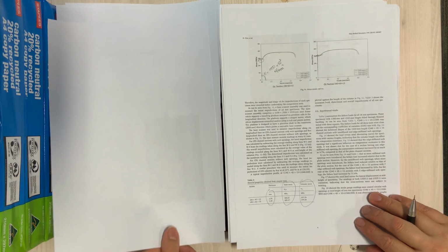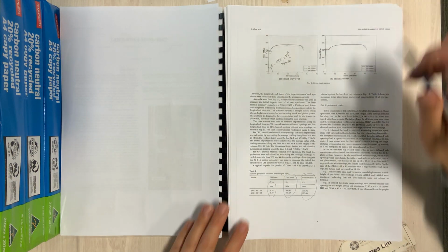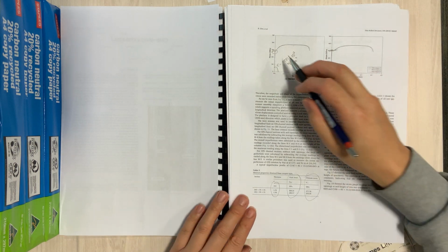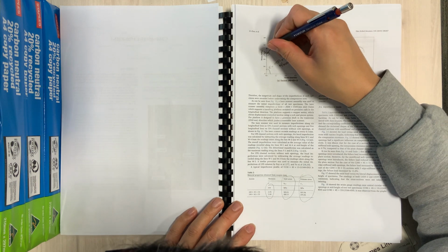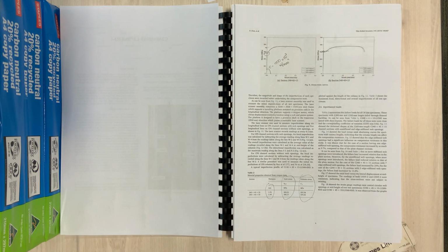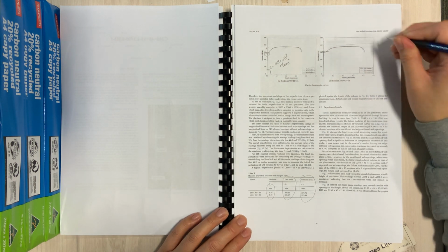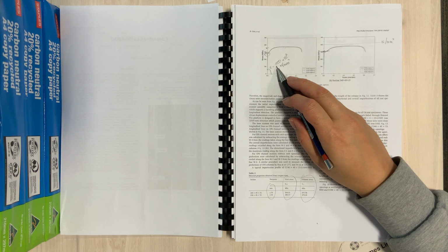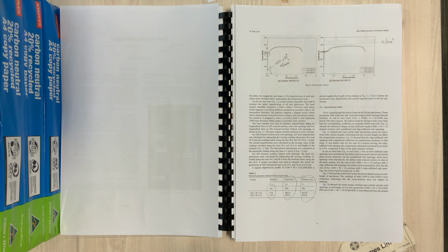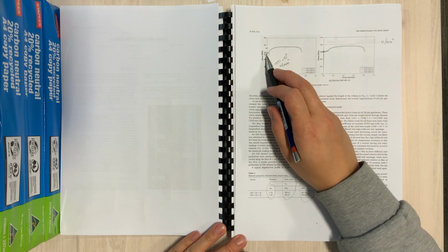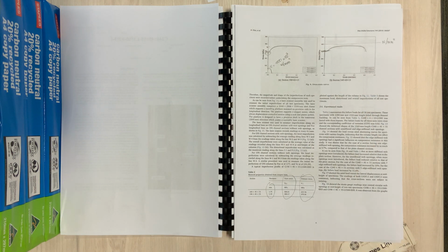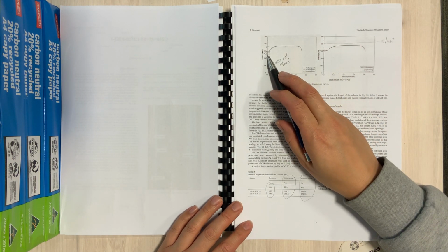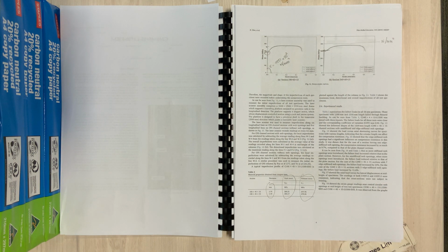eventually it would fracture. So when we do these experiments, we plot the stress strain curve, and we can see that for steel, the yield stress is maybe about, or the ultimate stress is maybe about 300, certainly less than 400 newtons per millimeter squared. So it's quite a nice idea to have these things in your head so that you've got a reference point. You know that the Young's modulus for steel is about 200 times 10 to the 3 newtons per millimeter squared, and you would know that your yield stress, of course, would be under the ultimate stress, and you would know that typical values would be about maybe 300, ranging all the way up to 500. But at least you know the ballpark figures for these things here.